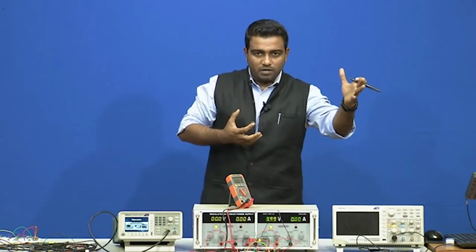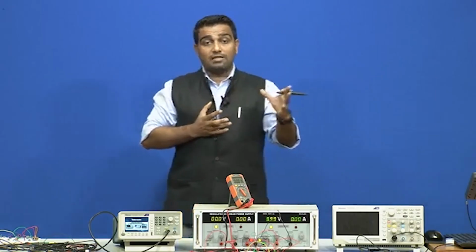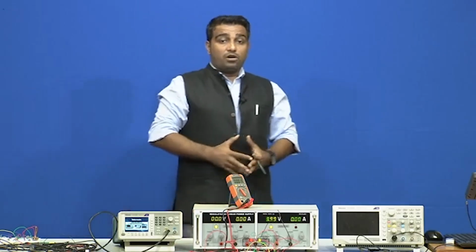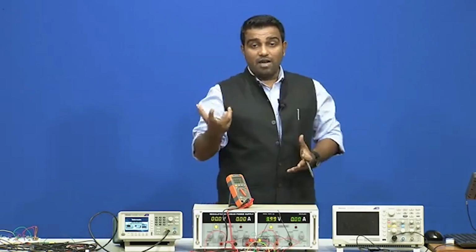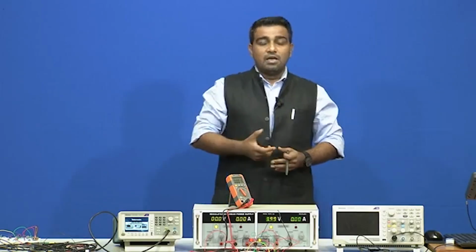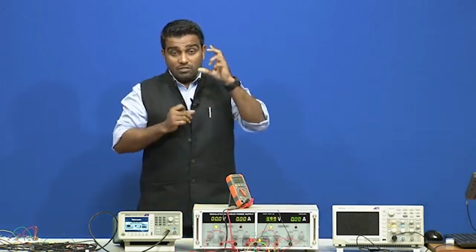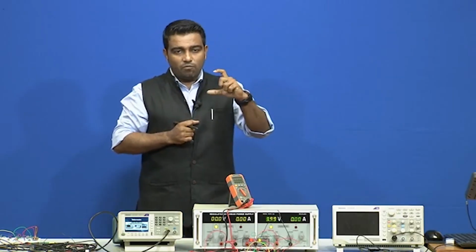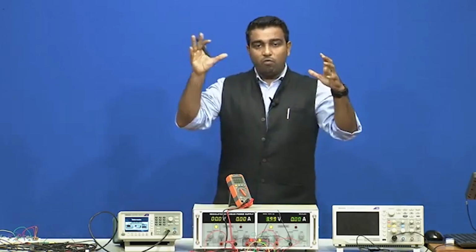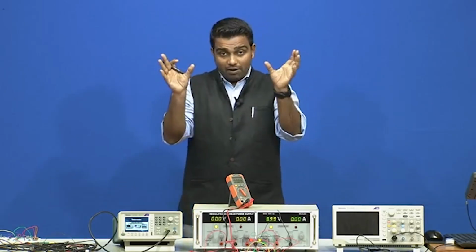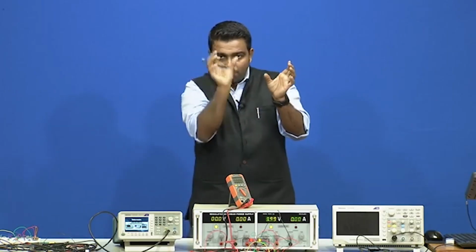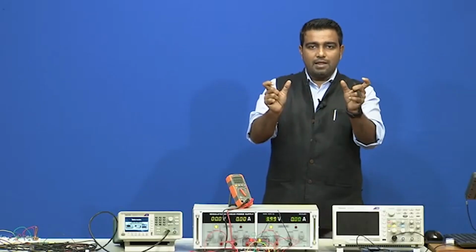At the loudspeaker, the final amplifier that is generally used is a common collector amplifier or voltage follower, and at the input is a common emitter amplifier or high input impedance amplifier. So, if I use the same voltage follower in the circuit where I have integrated the potential divider with the inverting amplifier, with a buffer voltage follower in between, can I reduce the loading effect? In the next module, let us see this particular experiment where we will use a buffer between the inverting amplifier and the potential divider.